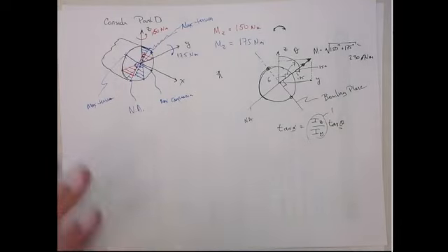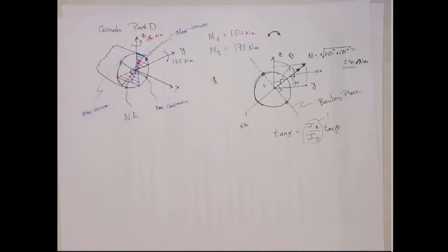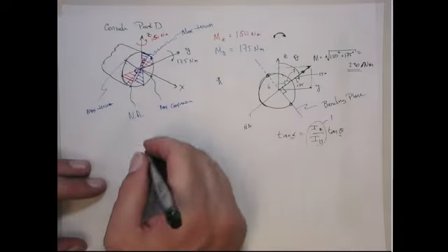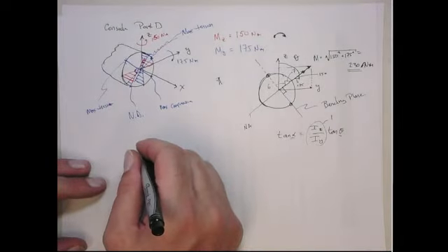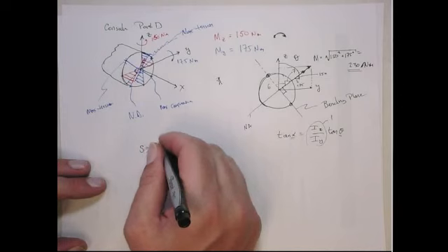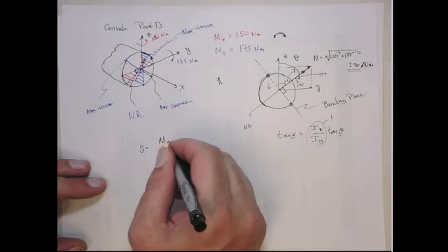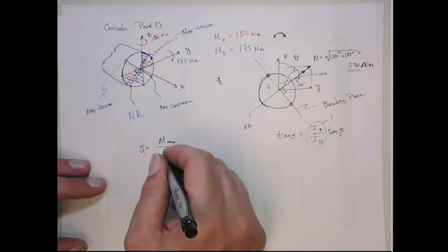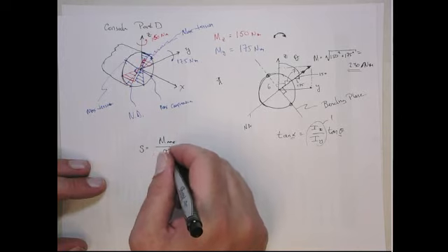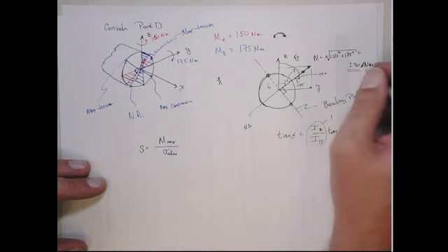So now actually I can treat this just as if it were a symmetric bending problem where the bending moment were 230, all right? So now I know that the shape factor has to be the maximum bending stress over the allowable stress. Now in this case, this is the max stress.